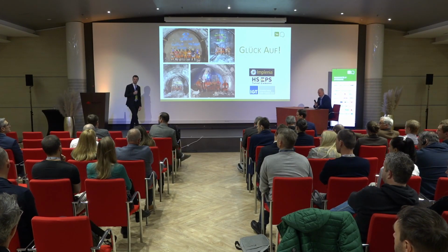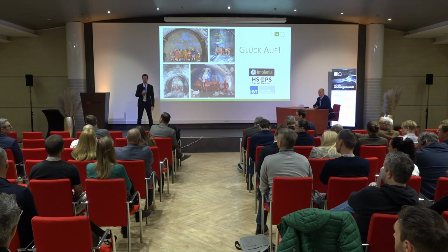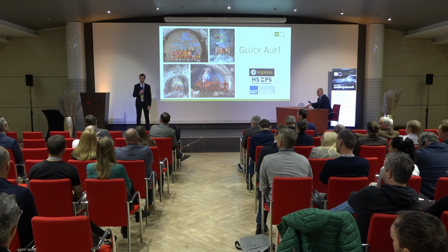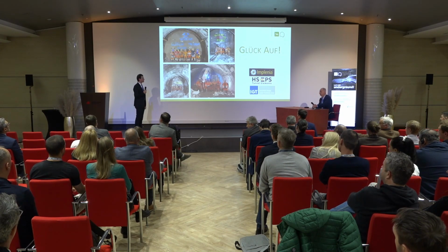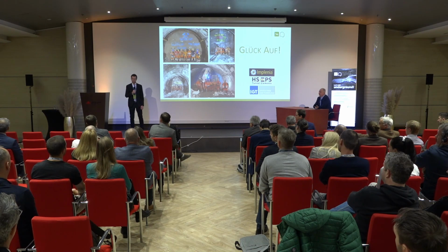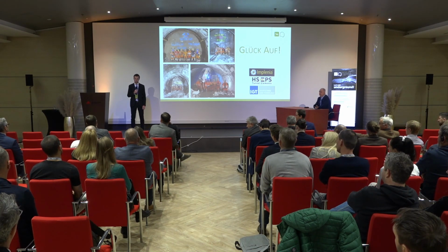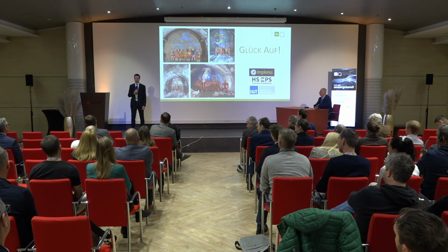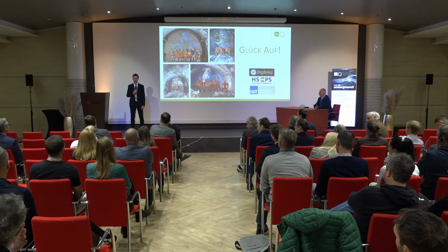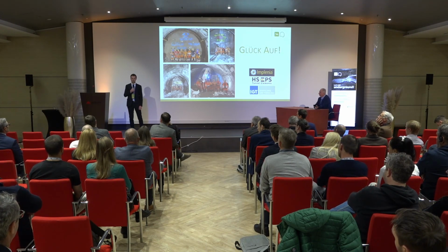Yes, Alan, please. Thank you for a really interesting presentation. Just looking at the pictures there, there's a lattice girder every meter, 1.3 meters. And then that's sprayed in, so you end up with a stiff line. Do you need the lattice girders? Could you use a fiber reinforced lining and then have a more continuous sort of softer lining?